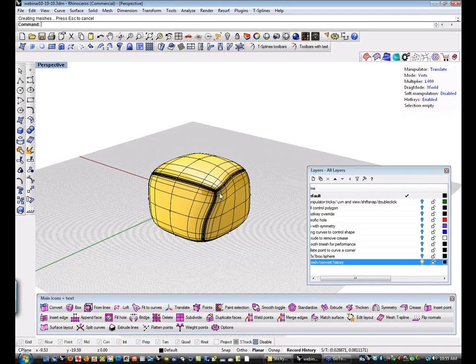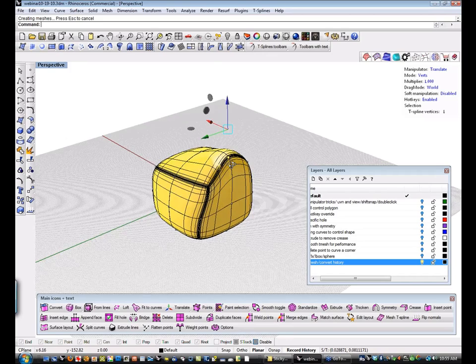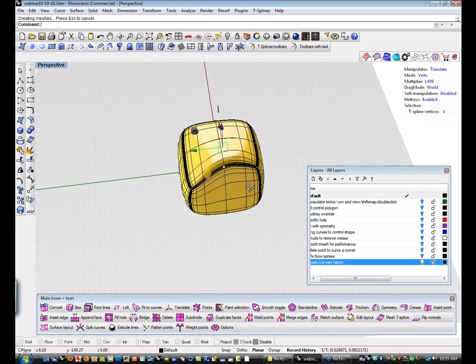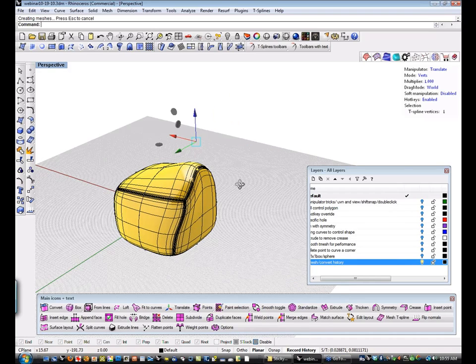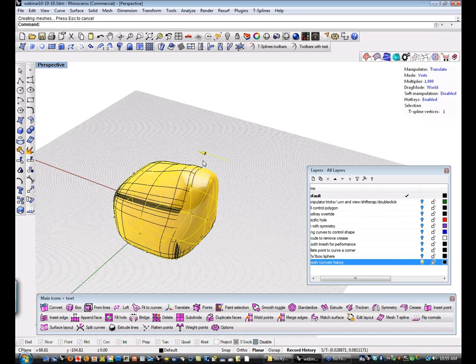These are historically linked. If I turn on my points and I pick a T Splines vertex and I drag this up, my Rhino poly surface updates. Again, this is really awesome if you're doing data transfer with somebody in Pro-E, SolidWorks, all this kind of stuff, and you send something down the line, since any type of imported data is going to be a dumb solid.